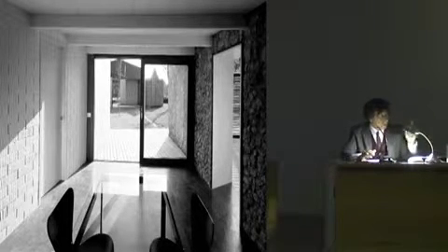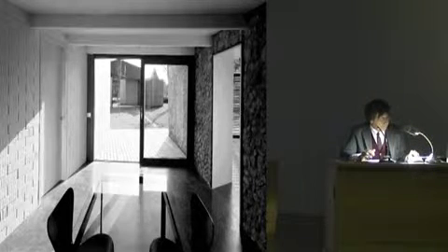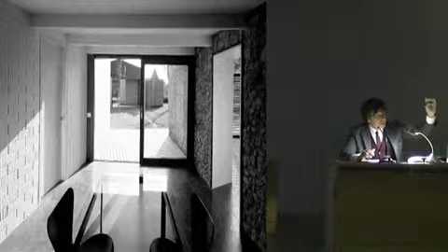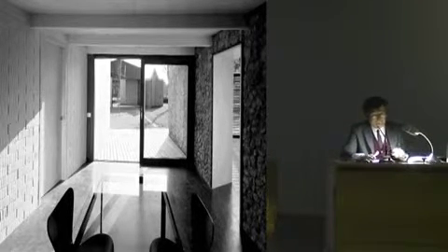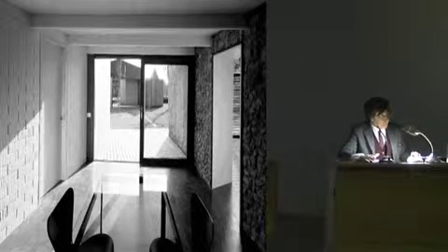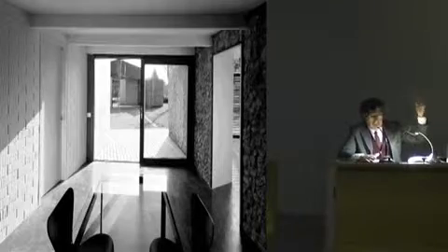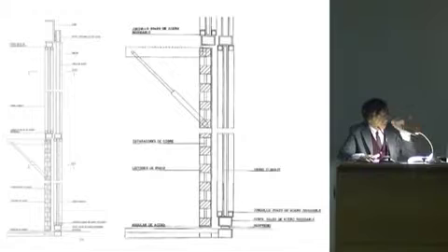Here you see inside, this is the wall made of perforated brick, and it's the load-bearing wall, and the other one is the stone wall. And you can see the structure, the beams, and the open roof plates. They're flat in this case, made of concrete, and then on top of that they receive the impermeabilization, isolation, and the final roof, and that's a detail.